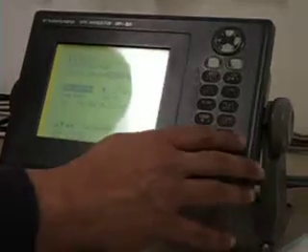But it says if you choose WGS 84, you have to put some correction because of a little bit of change. So I will put in the position offset, clear the old value. Look at the chart, 0.03 minutes south. So first is 0 because of the point, no need to put the point, 0.03. Now it is written north. To change to south, press the tone button, this button. By pressing this one, it will change north to south, east to west, or plus to minus. Anything you can do by this tone or toggle button. So it's south.